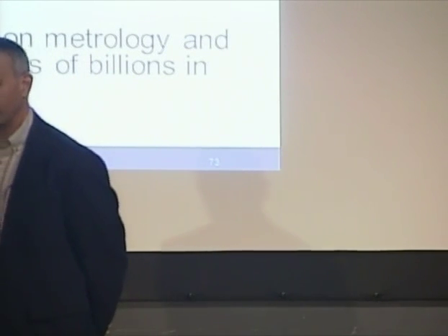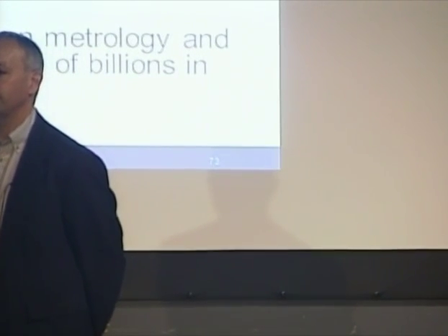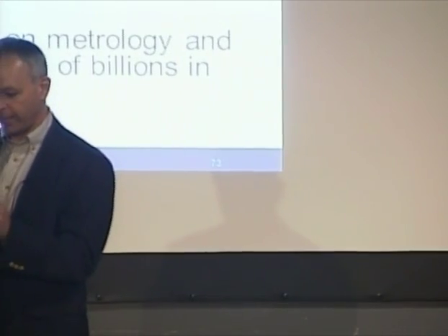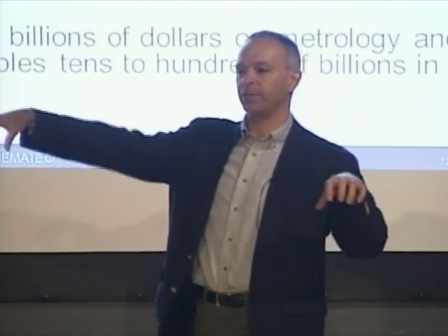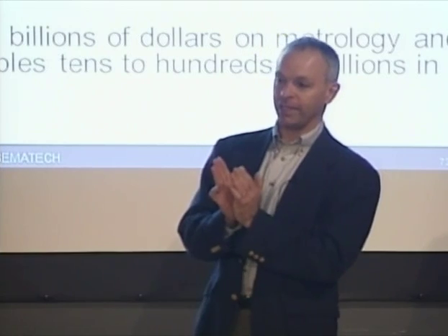What's being done with the roughness? You said that wasn't so much a problem when the gaps were bigger. Is that more of a surface tension issue where roughness isn't scaling down the same way that everything else is scaling down? Something like that. Part of it's probably also the polymers that are used in photoresist, that they have these photoacid generators there, and those acids diffuse a few nanometers when they're hit with light, which is what you're deliberately trying to do. So you've probably always had that kind of, based on the material, a few nanometer roughness in your line. It's just more evident as you shrink it.